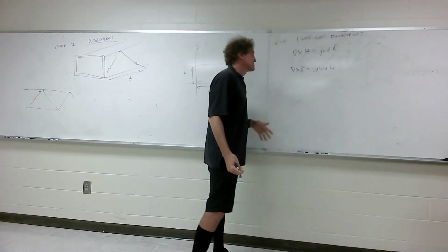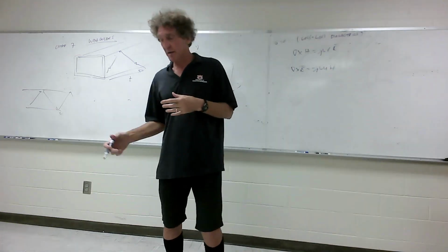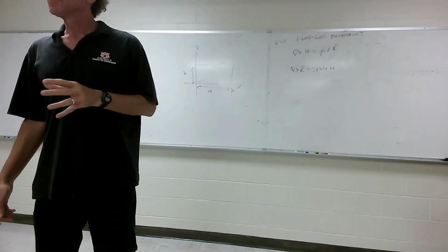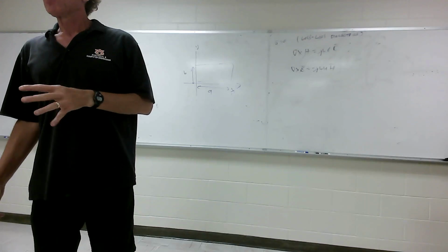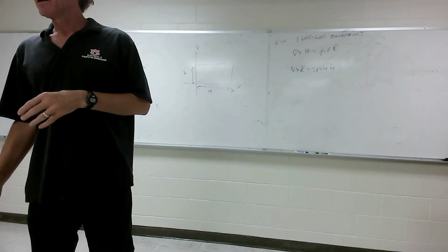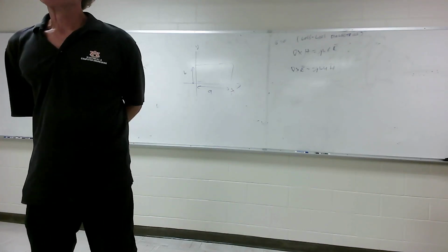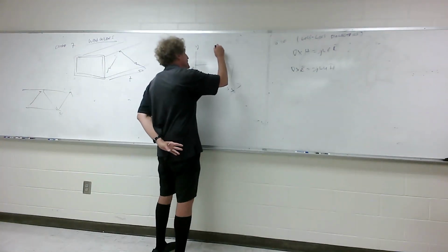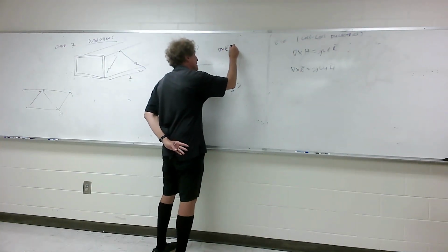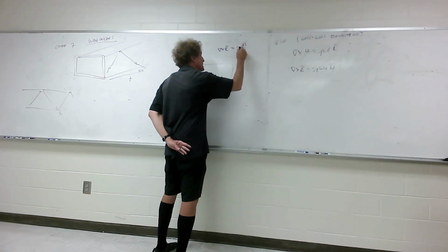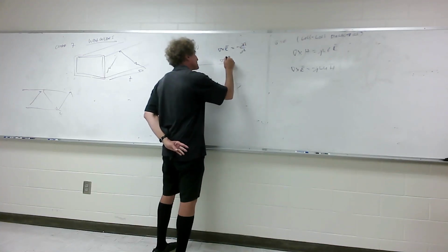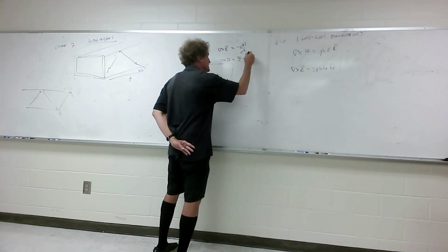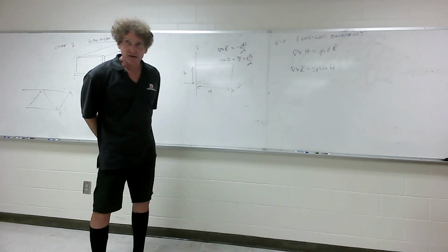Now I'm going right into the phasor domain. I could write it in the time domain, then make the necessary changes and say, now we're going to the phasor domain. But these are the two equations in the phasor domain for a lossless electromagnetic event. Here is the formal way: curl of E is minus dB/dt, and curl of H is equal to J plus the partial of D with respect to t. These are two fundamental equations.